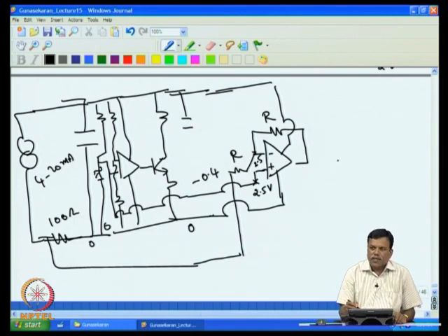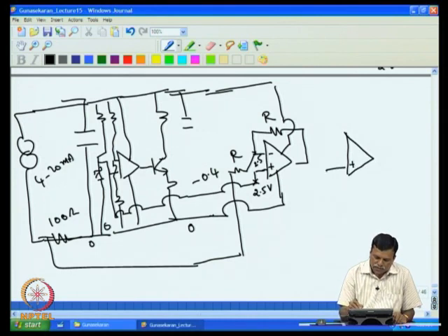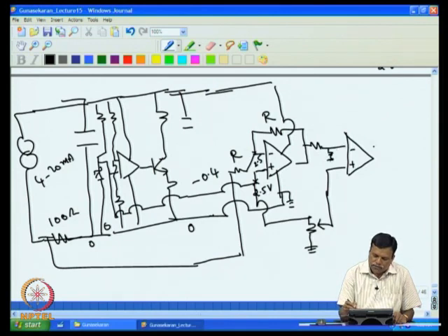So we take an example, that is, assume that we want to control an actuator. Then what we do is we compare this output voltage with the reference voltage. So if this reference is given to a positive input, which can be this itself. So I can have a reference, that is, this is our ground, so I connect this to ground, and then I can set this whatever value I want, and then this voltage, if it is very high, I can put a divider and suitably scale it down such that it matches with the reference.